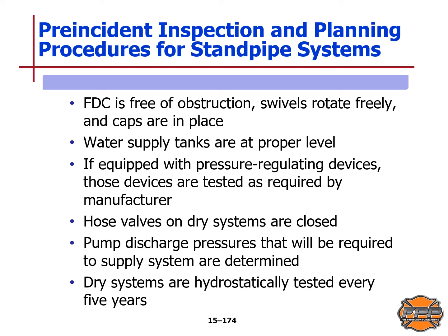Next, if equipped with high-pressure or pressure regulating devices, these devices are tested as required by the manufacturer. Next, hose valves on dry systems are closed. Then pump discharge pressures that will be required to supply the system are determined, and dry systems are hydrostatically tested every 5 years.